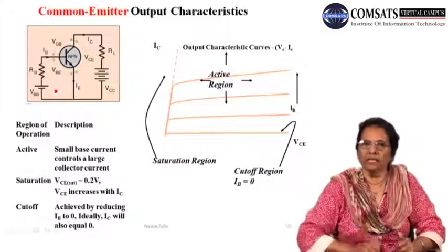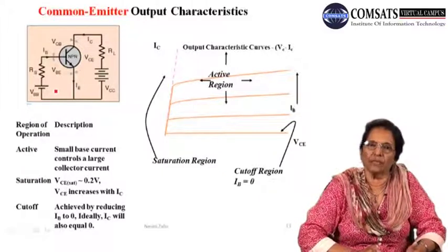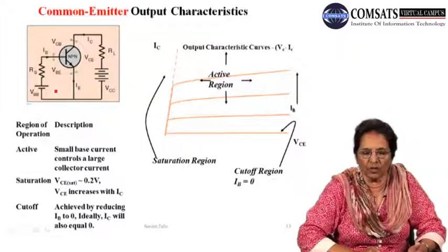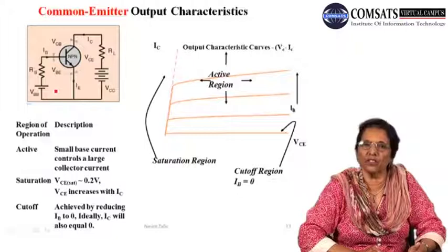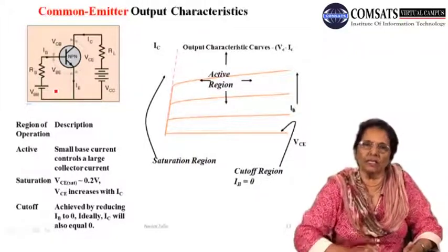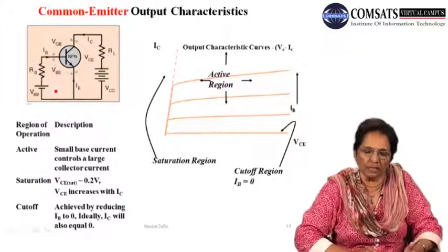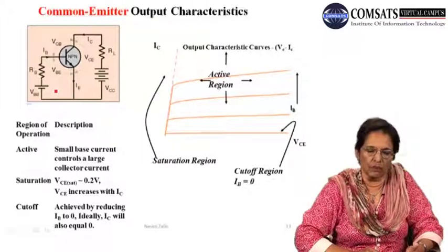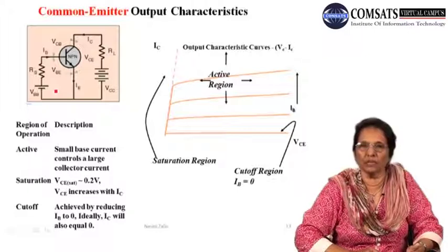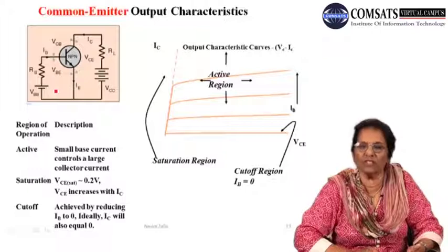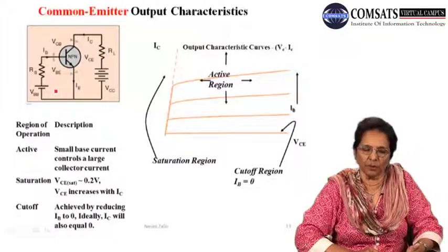Therefore, accordingly, the polarity is such that the emitter and base junction are forward biased, and similarly, the polarity of the collector and emitter is such that they have to be reverse biased. So you can see in the circuit symbol that the emitter base junction is forward biased with the bias VBB. The battery VBB is supplying forward bias potential, and VCC is supplying reverse bias potential.